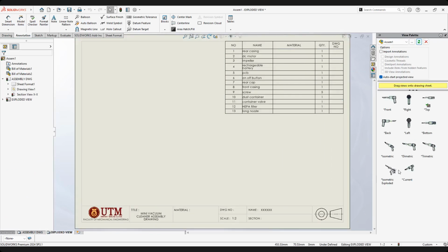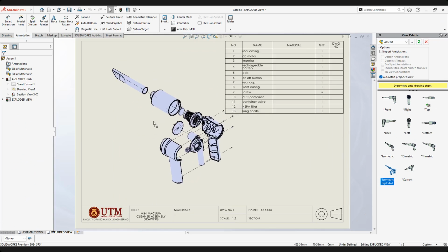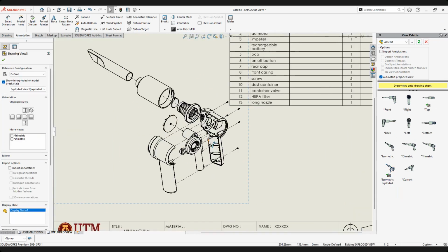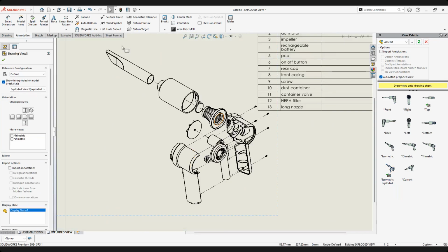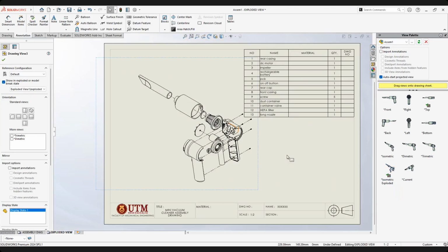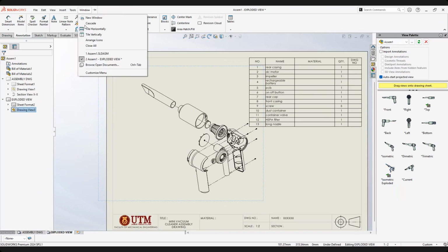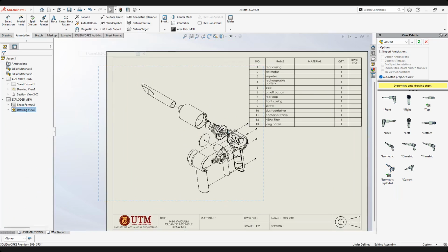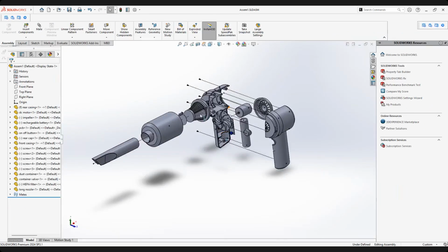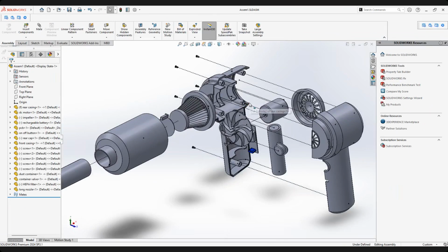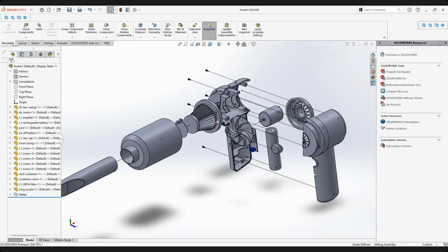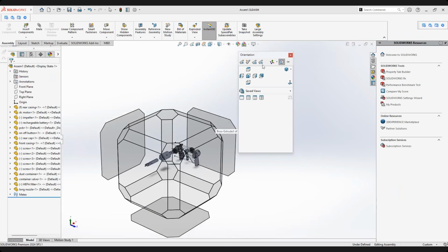Right. So can you see there is a menu called exploded isometric. I bring it to this one like this, right? So we have the exploded view. Do you want to keep this view angle or go to another? It depends. If you don't like this view angle, you can go to another view angle of your assembly view. To me, this angle is not good. You can save the view. For example, this view, you press spacebar. I want to name this one as a new view.